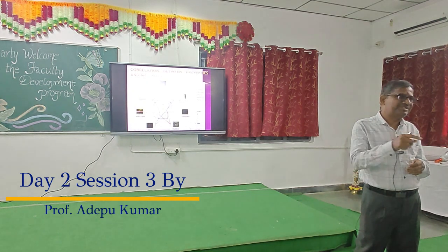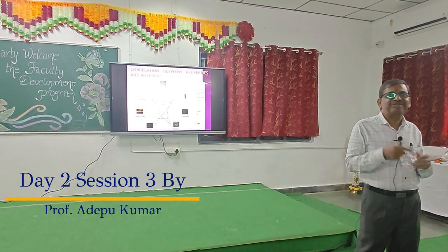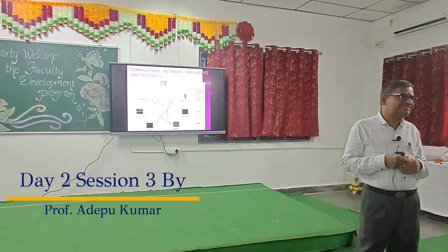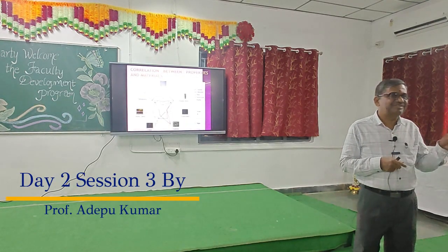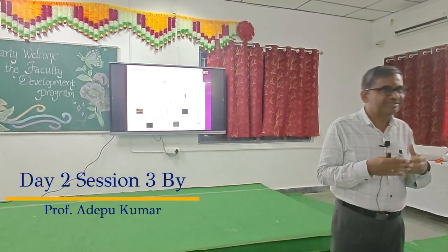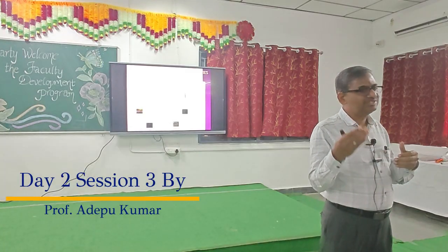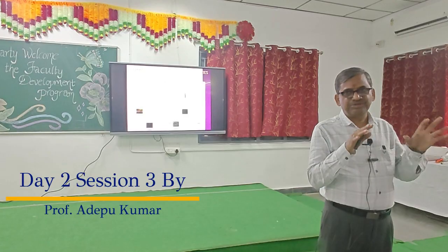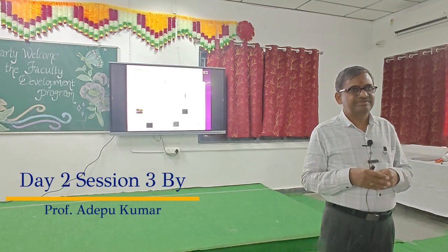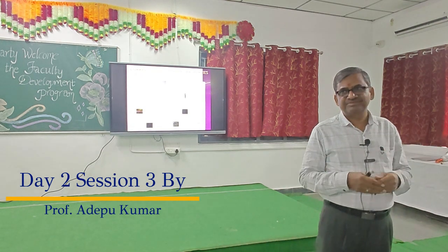So like that, one of my MTech students completely did failure analysis of copper to aluminium. So finally he succeeded at the end of his project. The solution is that three precipitates are formed during the combination of these two materials: Al2Cu, Al4Cu3, Al2Cu3. Because of these precipitates, cracking occurs. So once the weld is completed, within a fraction of seconds it will separate.